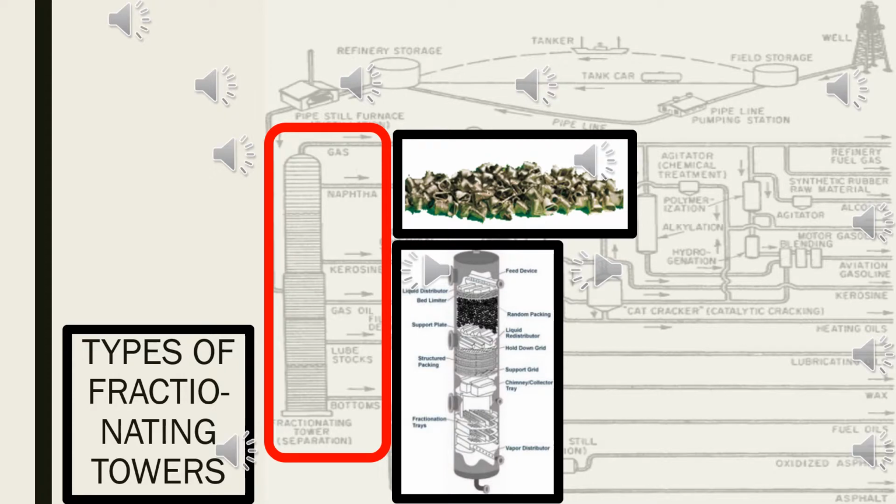The first type of packing material that is available to you is helipack, which is formed from a metal wire wound around a twisted rectangular rod. It has a free space of 83%. It is most commonly available in stainless steel but is also available in nichrome, monel, nickel, hastelloy, bronze, and tantalum.